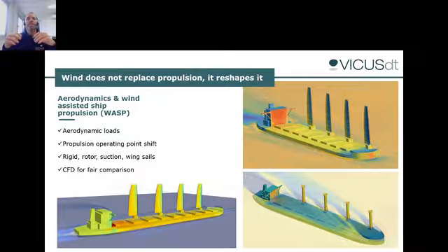But as we are propeller guys, we see more potential in how the sail interacts with the hull, and the hull with the propulsion and maneuvering, because when we have wind-assisted propulsion, we are putting an additional set of forces and moments over the hull that you can imagine is interacting with our hull that is being propelled through the water, and the course is controlled by the rudder.